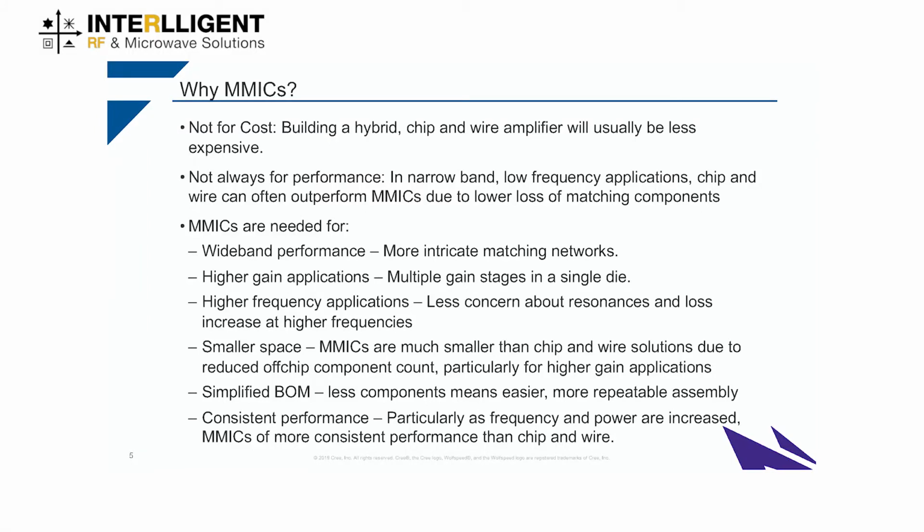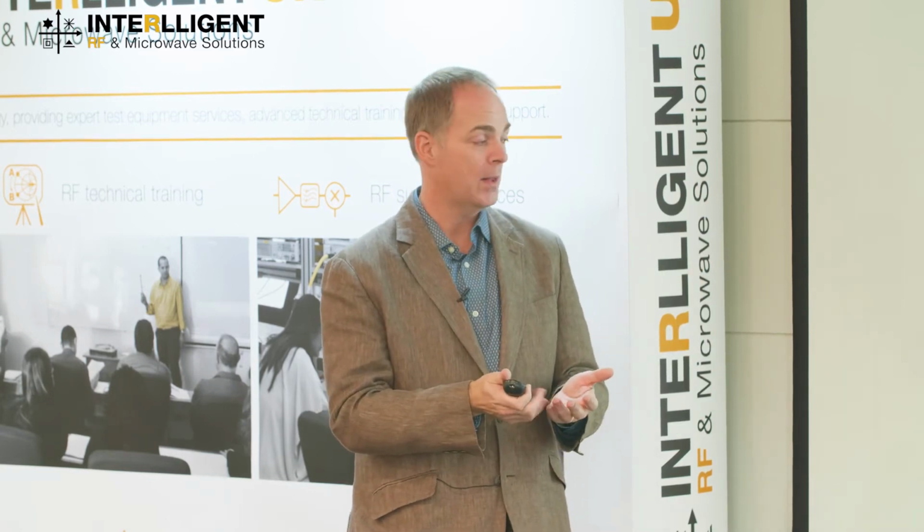So again, with a phased array, if you're putting these things into an array, you need to make sure that they are matched or at least can be calibrated out across the entire array. Being able to build these and properly bin them such that they work out of the box in a way that's well matched significantly simplifies the assembly.